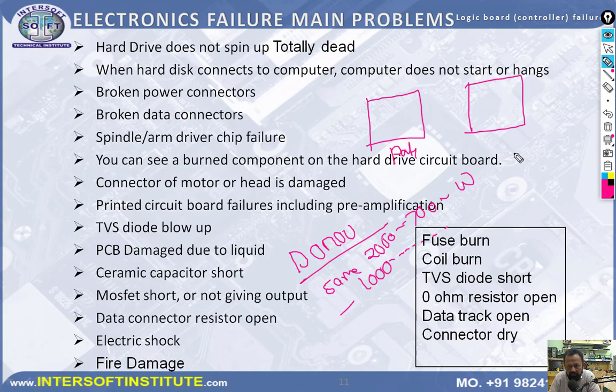This is our hard disk PCB which is dead, and we buy another PCB from a working hard disk. So this ROM we have to swap from here to here, and this to here. We want the patient ROM to be on the donor PCB, and then we can connect, like that. You will see how to do it if you buy a PCB from the market.